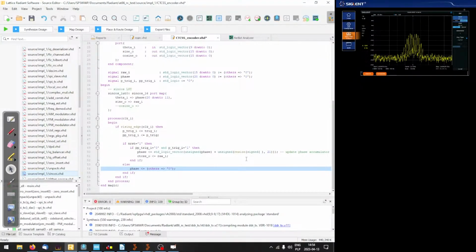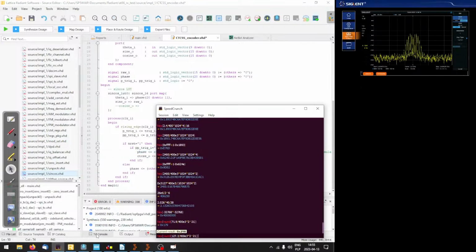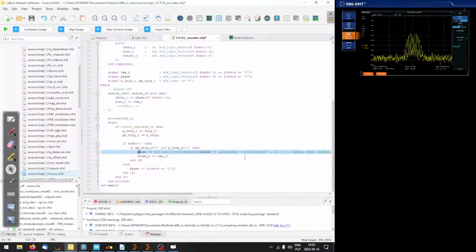All right. So now what we need is the value to use for the phase accumulator. So how to do that? Actually, we've got the phase word that is 21 bits, and we want to add, let's comment this out, we want to add this word to 29B.